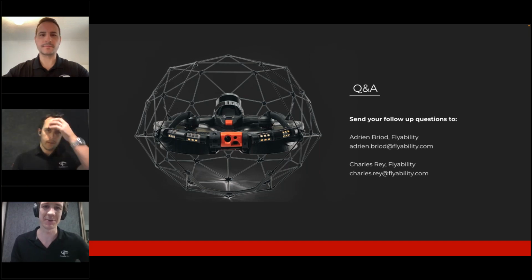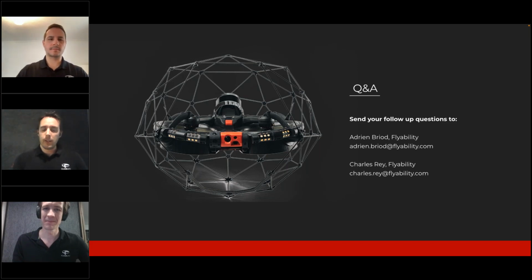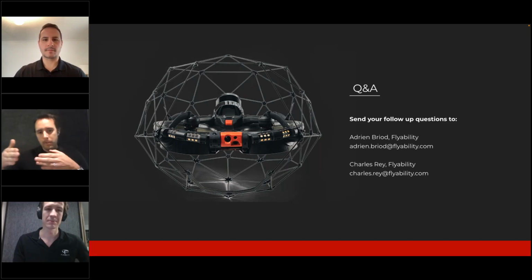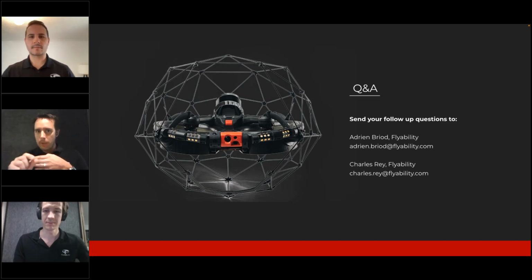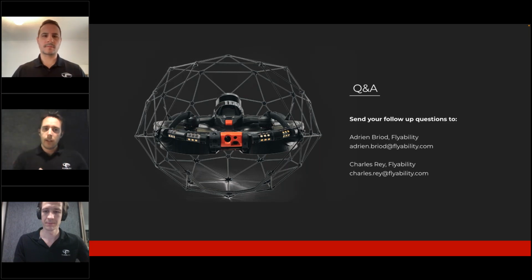And then, Charles, you have something to add? To add something, also to see where your crack really starts and where it finishes, we are using the side lighting to have oblique lighting, to really see where it starts by playing with the shades. That would also help you to see where it starts and where it ends. And that could help, by taking the POI as Adrien said, to use your point cloud to measure the distance and the size of it, the length of it, sorry.